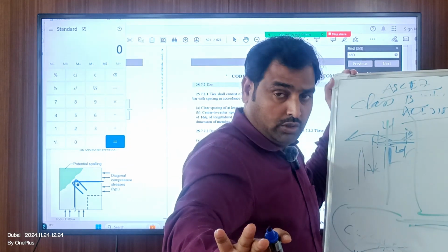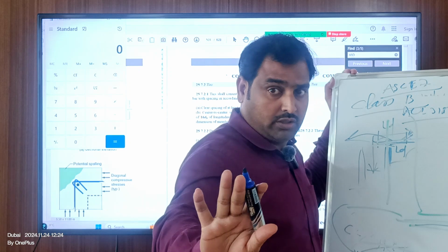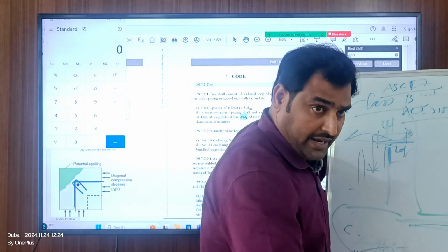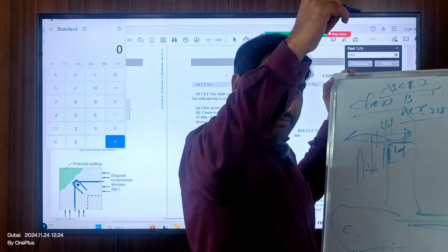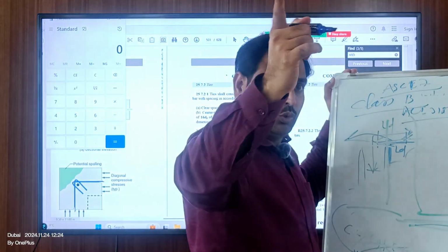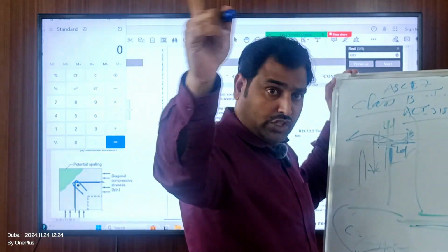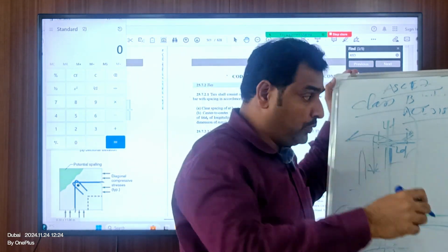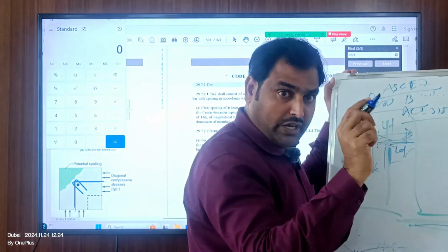It is not going to take it as a pin connection. For the pin connection, you need to assign the pin support at the base or at any other element, be it column, or beams connected to slabs, or beams connected to columns. By default it is assumed as fixed, or you need to release the moment actually.